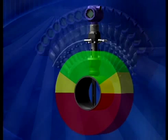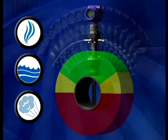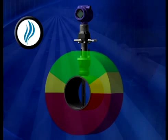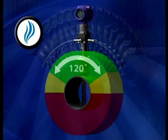The second main consideration of Annubar installation is to mount the flow meter in the correct orientation on the pipe. The orientation will depend on whether the process fluid is a dry gas, liquid, or steam. In horizontal pipes for gas applications, always mount the Annubar flow meter on top of the pipe, within a 120-degree recommended zone. This ensures there will be no condensate trapped in the flow meter or impulse piping.